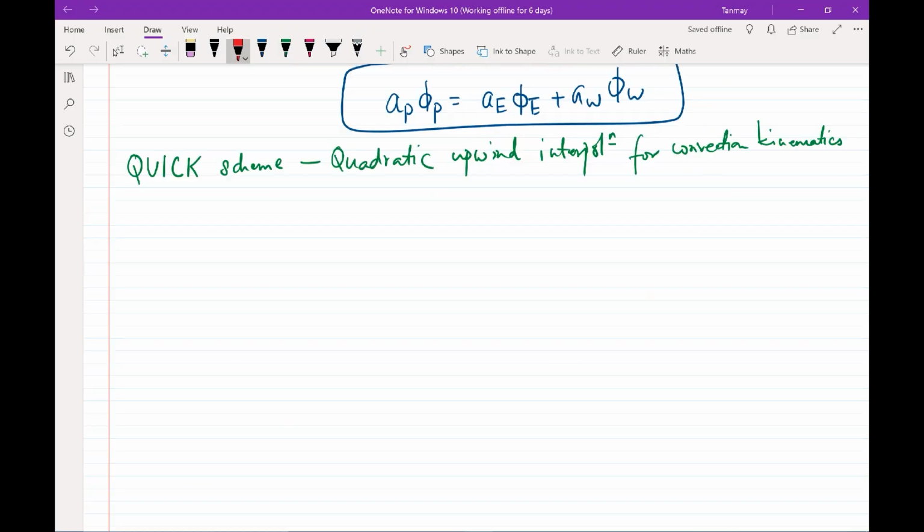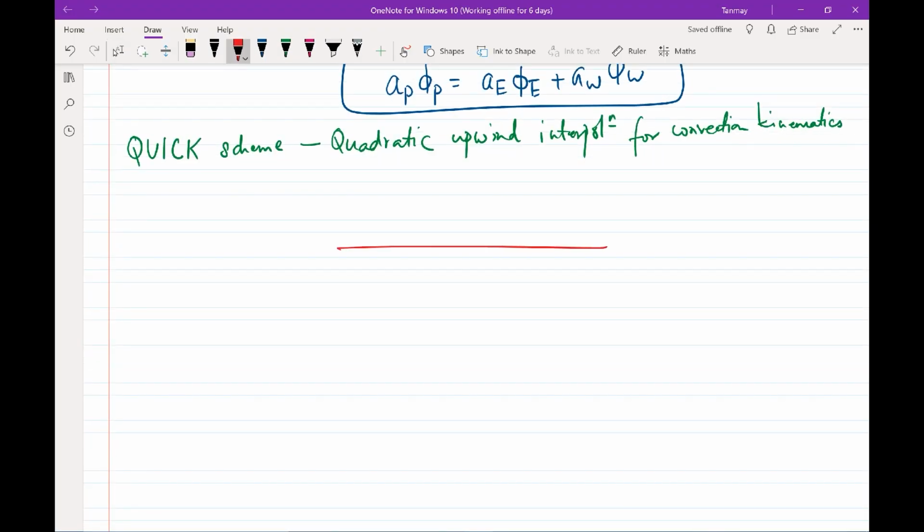We said that the upwind value is exactly the same, but in the QUICK scheme we want to improve the robustness of the scheme, so we consider more points on the upstream and the downstream side, which I would be showing you later. So let us say we have the same problem. We have this P, we have this capital E and capital W. So let us consider the case of when U is greater than 0. So let us say we want to investigate this small e point.